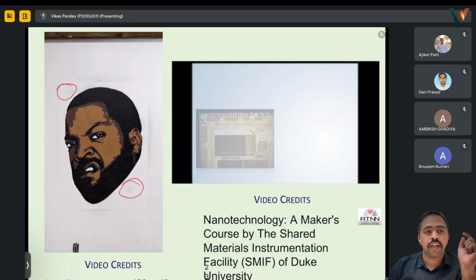For lithography there are options: positive and negative photoresist. For positive photoresist, the area that is exposed will be removed. Negative is a little tougher: the exposed area will remain. We have just seen that the area that gets exposed is removed for positive, while for negative photoresist it remains there because it is hardening.